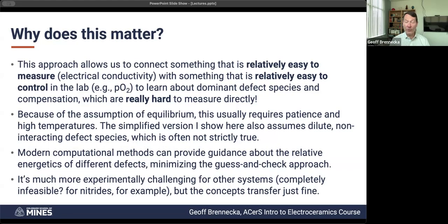In AC, there's also going to be noise, but you at least have the added tool in your toolbox of using a lock-in amplifier and saying, right at exactly this frequency, I'm expecting to see something, and so I'm going to ignore everything that doesn't sit right at that frequency, and then I can shift over to another frequency. It makes it a little bit easier to pull out tiny signals from noisy backgrounds. So that's the kind of thing that I would use in that case.